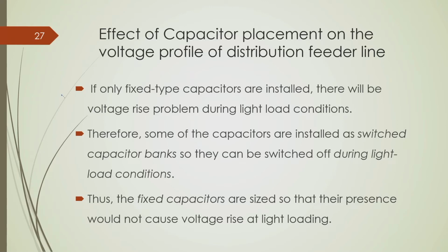So, this is what I am exactly trying to make you understand, that only fixed capacitive compensation, or only fixed type capacitor installment, will lead to the voltage rise problem during light load condition. Okay.